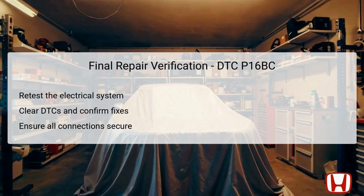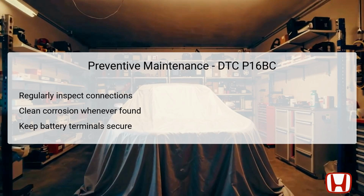Clear any DTCs with the HDS and observe for recurrences during operation. Additionally, double-check all connections made during repairs to verify their security and integrity, as loose connections can lead to recurrence of issues. A thorough review of the system will confirm that the DTC has been resolved, ensuring longevity and reliability in vehicle performance. Preventive maintenance plays a significant role in avoiding DTC P16BC and similar issues in the future.